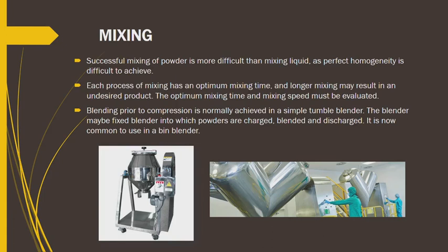Each process of mixing has an optimum mixing time, and longer mixing may result in undesired product. The optimum mixing time and mixing speed must be evaluated. Over-mixing can cause problems in the formulation of the product and the tablets.